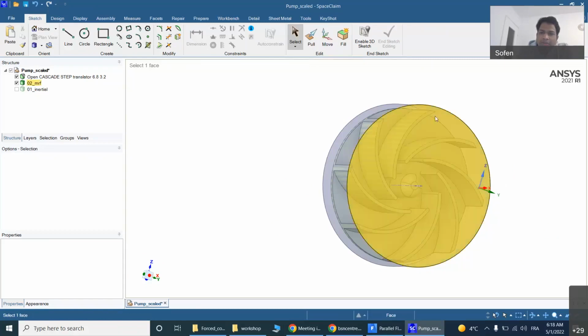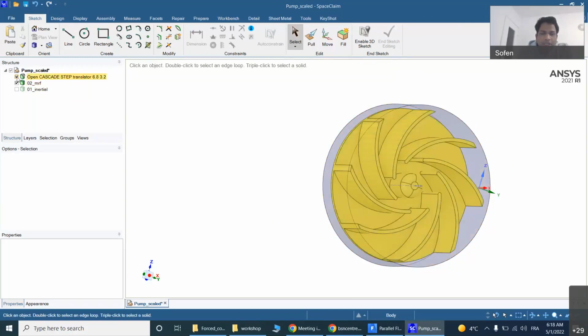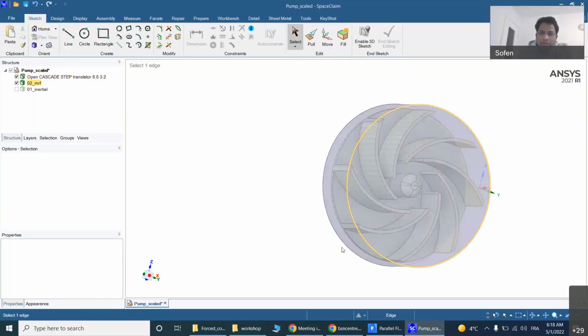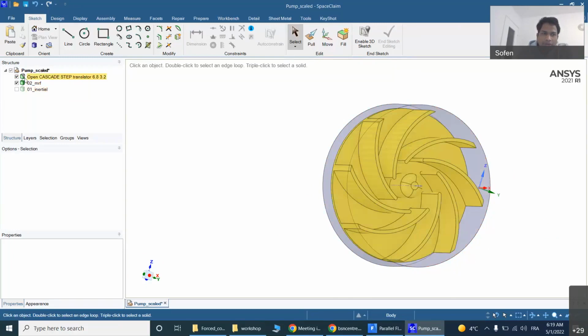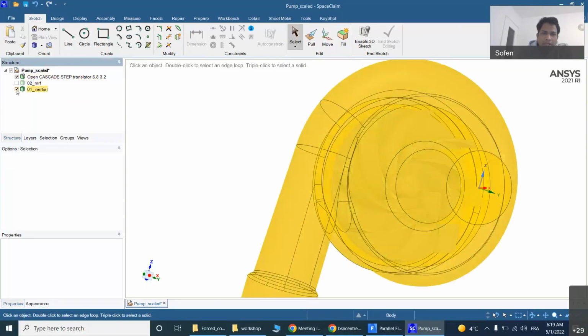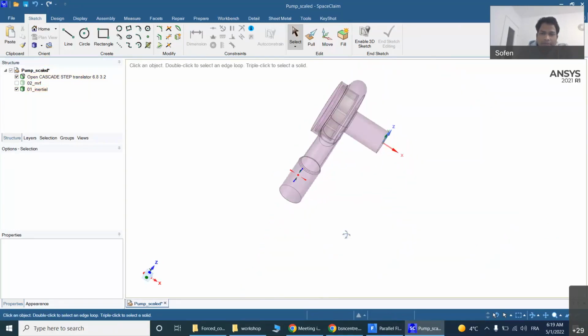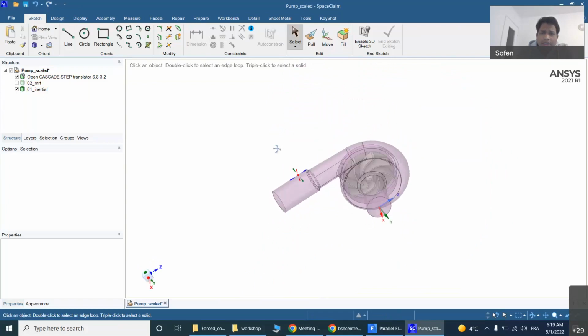We need only the fluid portion. So we take the solid cutout from the fluid, as if there is fluid surrounding that solid blade, and we make it a non-inertial frame, where we apply the additional terms and solve the whole Navier-Stokes equation, while in the rest of the domain we are solving only the Navier-Stokes equation, right?